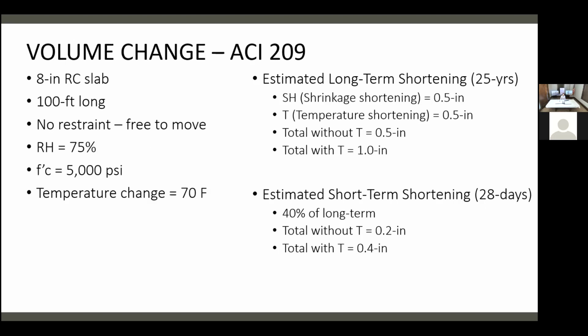And in the colder climates, when you're doing work in the wintertime, the contractors will pull all that heat after a couple of days when the concrete reaches 2,000 or 3,000 PSI. The problem is that concrete that had the heat pulled from it will still undergo the temperature change. So temperature change has a big impact on your structure. I know a lot of engineers who want the building envelope up first prior to filling in the pour strip. So that's interesting.